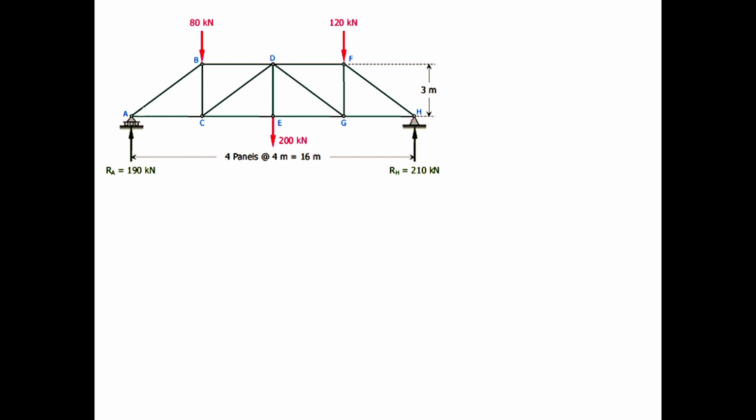Okay, so next, since we already solved this one, this one is in compression. This one is 350 kilonewtons. Then this one is in tension, 280 kilonewtons. So if we try to observe the next joints, F and then G. If you're going to hop onto the G joint, our unknown members are three, diba? Member FG, member DG, and member EG.